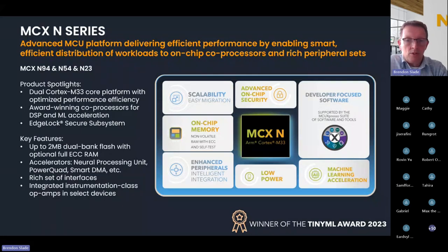And this is all built on, as all the devices are, a 40 nanometer process that's optimized for both active and leakage power. And then security-wise, it's PSA level 2 certified at this point, looking to be certified higher than that. We're investigating that now. And we have a high-performance crypto engine, on-the-fly memory encryption, decryption, and tamper detection.